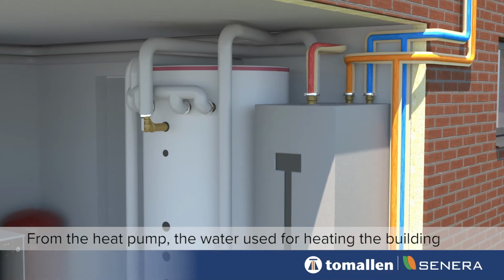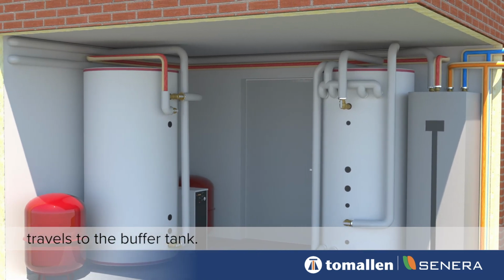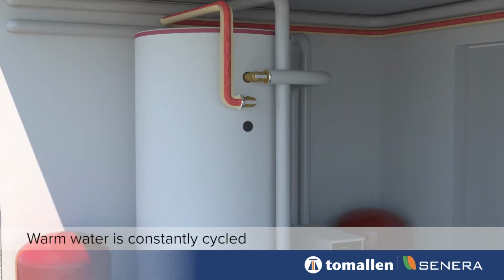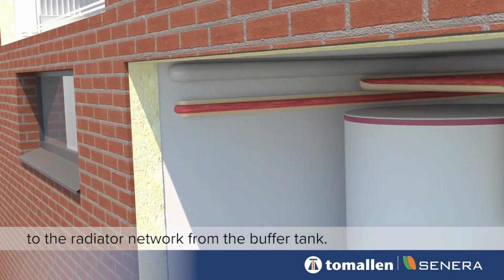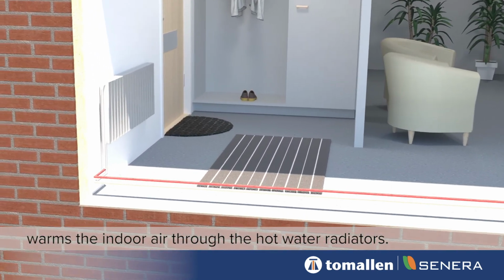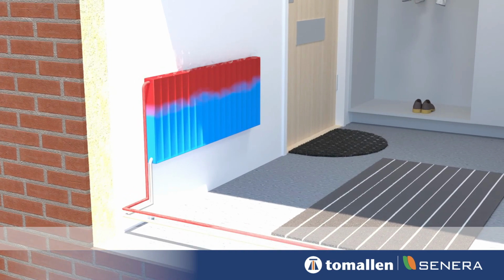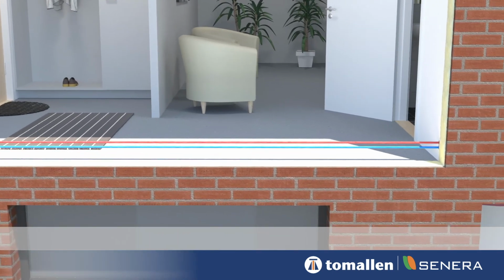From the heat pump, the water used for heating the building travels to the buffer tank. Warm water is constantly cycled to the radiator network from the buffer tank. The warm water travels to the apartments and warms the indoor air through the hot water radiators. When the water cools down, it returns to the heat pump.